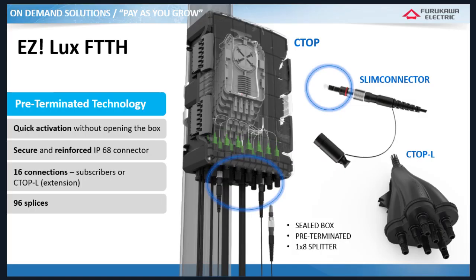The next option is to use connectors that are just plug and play. So in this situation, you don't even have to assemble the connector in the field. You just go and plug and play. You plug the network side, let's say, which is this one, and then you have another end that you use that field installed connector to connect the customer.